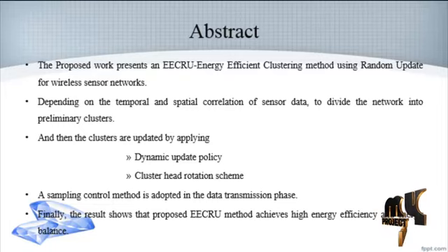A wireless sensor network usually contains a large number of smart wireless sensor nodes that are small in size and operate on low power. Energy resources are often limited in wireless sensor networks, especially in certain applications where external energy supply is not available. Thus energy efficiency has become an emphasis of the research. Sensor nodes usually have temporal and spatial correlation of sensor data. This results in data redundancy, so 80% of the node power spent transmitting redundant data is a waste of energy.